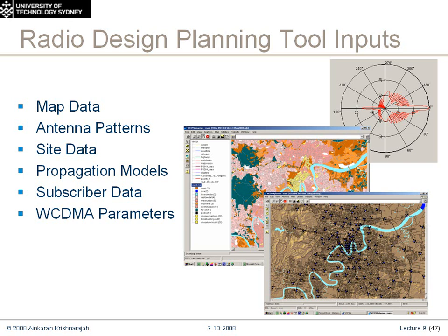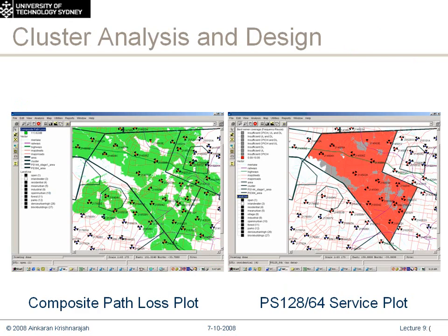So you'll see here in the pictures on slide 47, you see the little black spots. Those are actually the base stations. And you'll see in the next slide a little bit more clearly 3 little triangles around a circle. That circle, or the red circle, is the base station site itself, the location of it. And the 3 triangles actually represent the 3 sectors. And you can see the direction in which the sectors are pointing based on their orientation in the map.